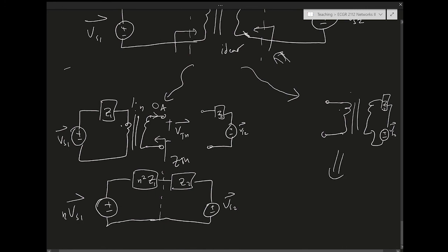With the current at 0, the voltage is going to be stepped down, because we're going opposite, from the secondary to the primary. So the voltage is stepped down by N: VS2 divided by N. And the Thevenin impedance is just a matter of finding the reflected Z2 impedance. Here we're reflecting from the secondary to the primary, so our equation still follows, which is Z2 over N squared.